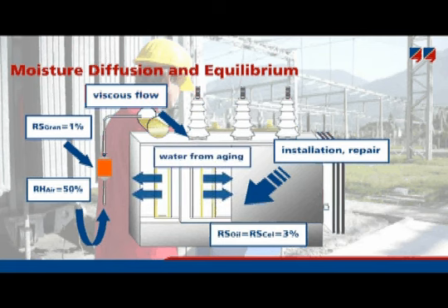So, water is a self-perpetuating entity. If there is water in the transformer, the water concentration will increase faster and faster because of the aging process, which is accelerated by water, and which will produce even more water. It is a self-accelerating or autocatalytic process.